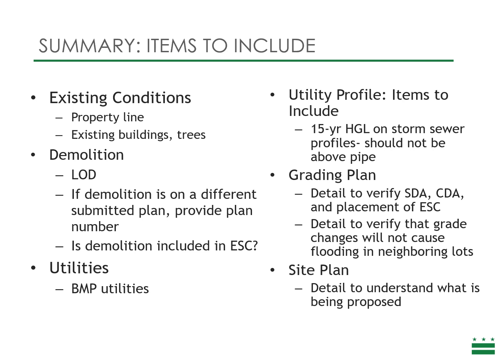above the pipe. For your grading sheets, include enough detail to verify site drainage area, contributing drainage area, and placements of erosion sediment control, and show enough detail to verify that grade changes will not cause flooding in neighboring lots. For your site plans, it's important to include details to understand exactly what is being proposed on the project and how stormwater management is being proposed as well.